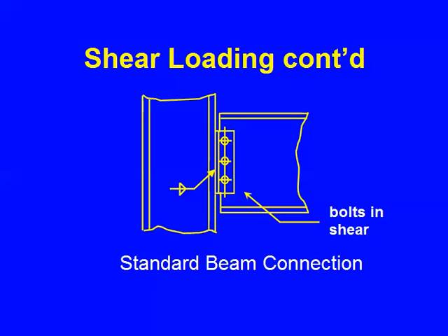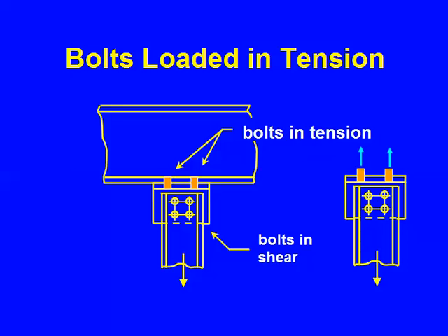This is a pretty obvious example. Occurs occasionally. A hanger, bottom flange of a W shape, and there's a channel and there's a T. The channel is here. The load passes out of the channel, in this case by 4 bolts, by shear, free body diagrams. Now it's in the stem of the T. From the T it has to head on up into the lower flange of the W shape. And that's the orangey bolts that we see here. I'll draw one free body diagram just so we can reinforce some of the things I've said.